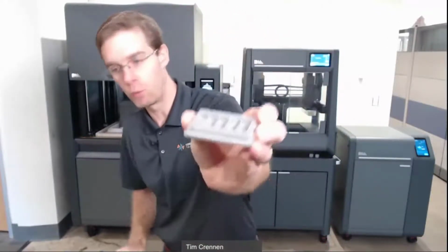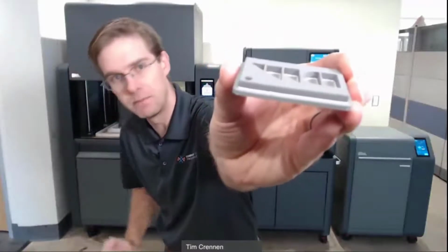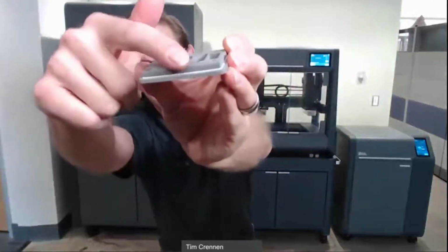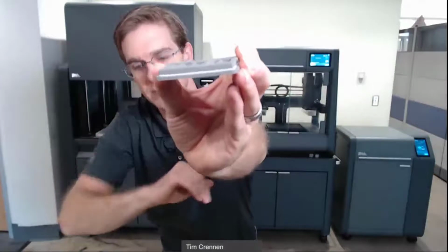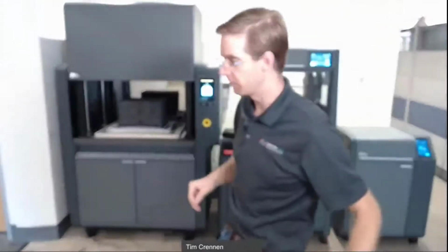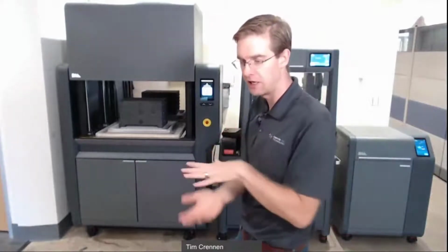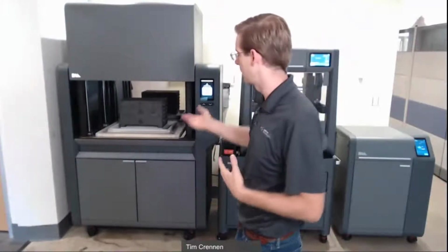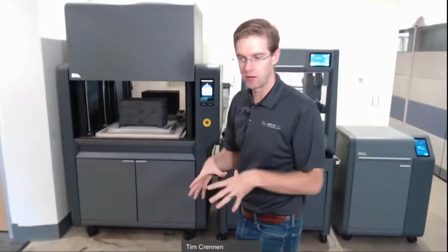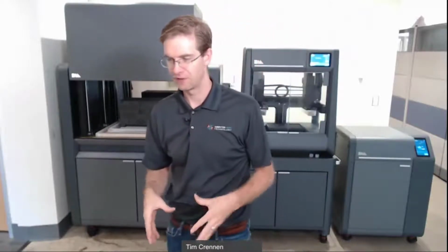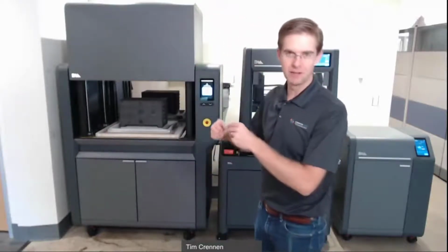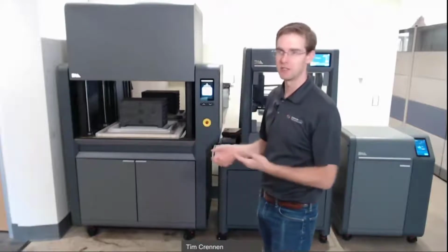There's a little white line in between this base plate and the actual part, and that's the interface material. So once we put it in the furnace to sinter, that powderizes down into a ceramic powder, keeps the two parts from fusing, and then when we take it out, we just drop it on the ground and basically separate the parts.